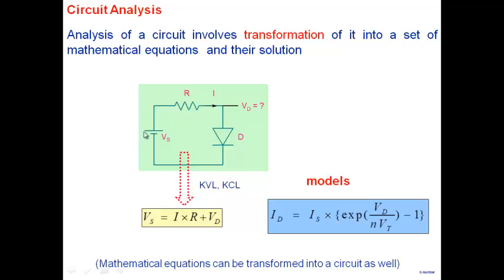The diode would start driving the current here. Obviously, it's not valid. When the voltage Vs is 0.6, and you approximate the diode by a 0.7 volt battery, that model is not applicable there. It's going to give you all wrong results. So we have to know where to apply that 0.7 volt model and where not to apply. Sometimes we miss that, and we start getting weird results.